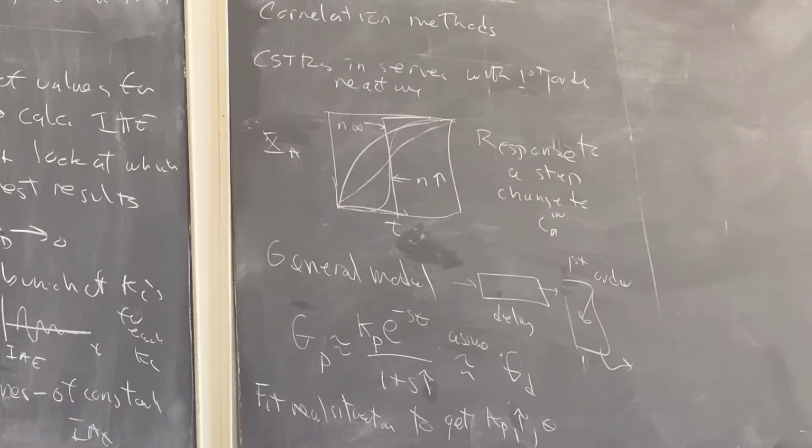For example, if you're doing flow through a pipe, you don't vary the velocity, the viscosity, the density, and the length scale separately. You see that they come together as a Reynolds number. The physics only depends on that combination, the Reynolds number. So here you want to do that also, to minimize the number of computer experiments that you need to do.